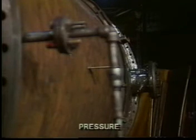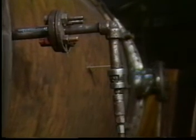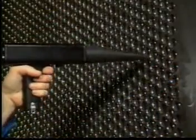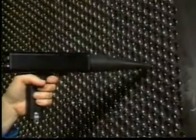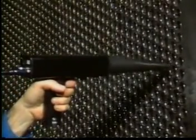The pressure method is conducted by first sealing up outlets to prevent the gas from escaping and connecting house air to the inlet. The system is then pressurized. Test the system as previously demonstrated. Listen for the characteristic rushing sound of a leak with the Ultraprobe scanning module.